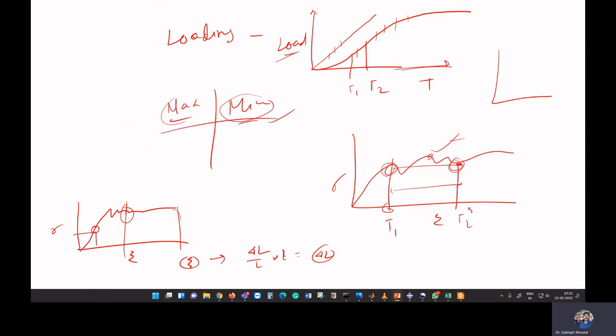Okay, so you have to give the loading in such a way that your analysis will go this much amount of displacement. Your analysis or structure will deform this much. If you are going for displacement control, in that case your delta L, the displacement, you have to specify such that it reaches your nonlinear zone, and you are getting a good result.